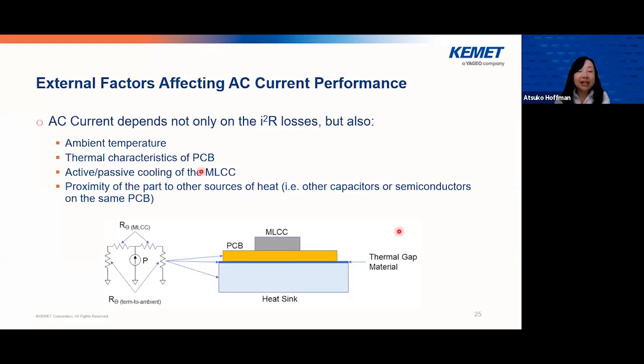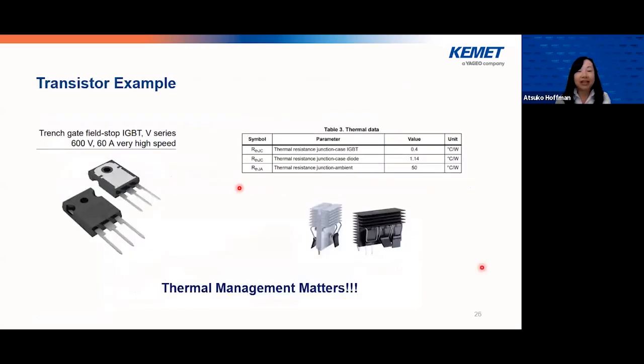Now, we have seen customers using MLCC at very high power levels these days because of the wide band gap semiconductors coming along. And you'll be surprised, designers do not think about the thermal management for the MLCC, how to get the heat out from the MLCC, but it is very, very important.